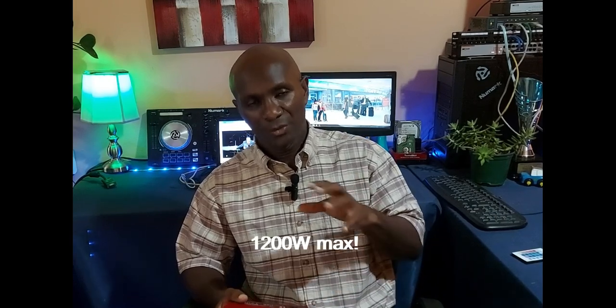You also have to check the surge or the peak wattage before you go putting it on that. And remember, I've spoken about buffer before. So this 1500 watt inverter, really and truly, I should not be putting load. The total load that I should be putting on this should be in the region of about 1200 watts.